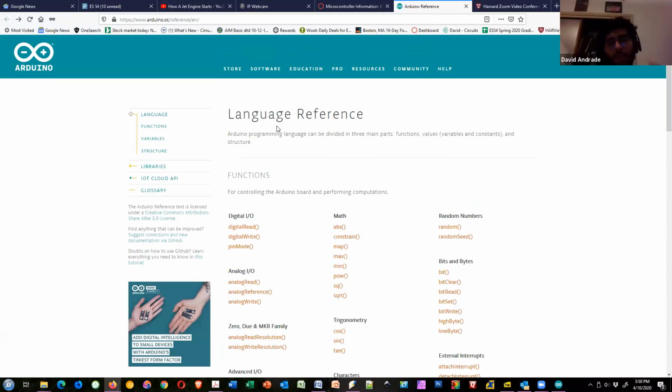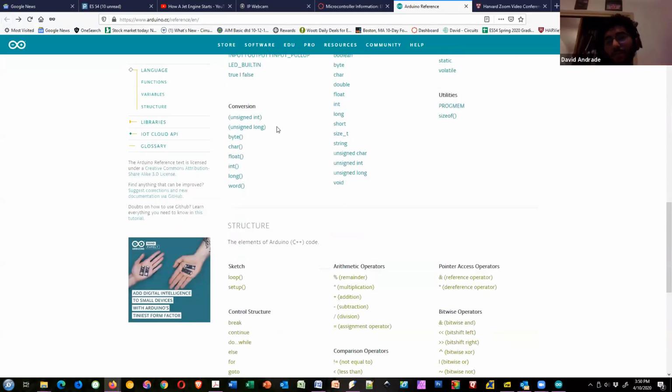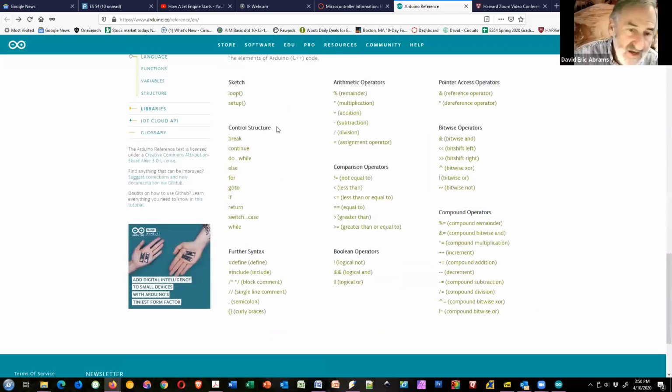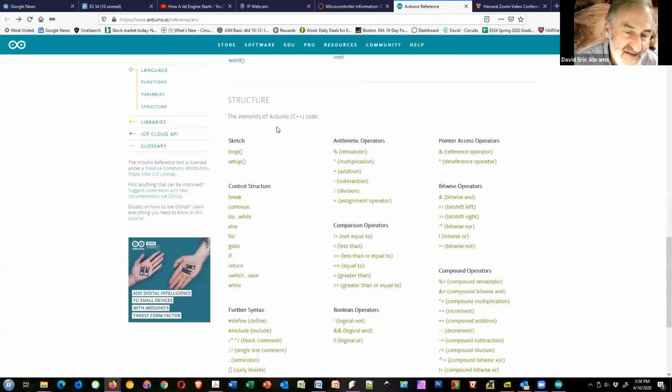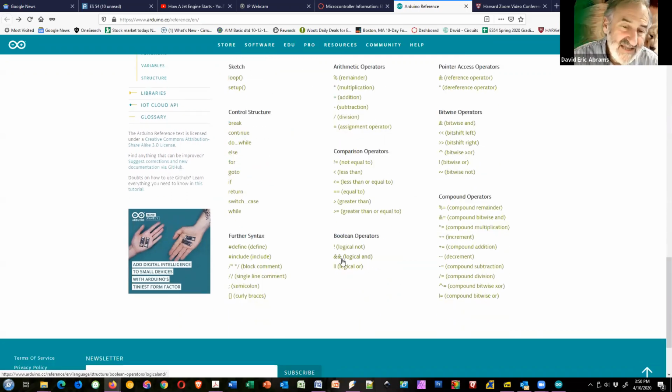So like those 3 operators you just told us are like gates. Are there like NAND gates, quote unquote, or would you have to use like a? No, there's not NAND gates. If you really needed a NAND, you could do an AND and a NOT. But it turns out that in software, you rarely have to do that. In software, you don't have the limitation of active low signals. So typically, you just invert a signal if you need to invert it. If you really need a NAND, you'd take the logical AND of 2 things and then take the inversion of it.